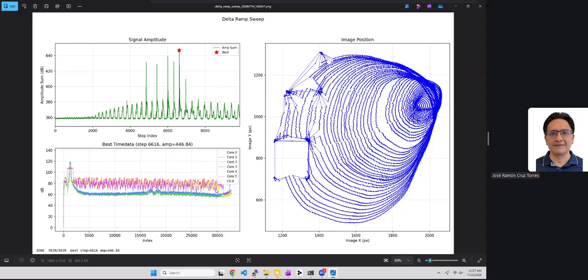It starts running immediately on the equipment. It starts from where it currently is and just starts spiraling out. You can bias it. If you want to scan over here, you can move your end face such that it starts here and the scan will start from here. Although, make sure it's still within the actuator's range of motion or you'll start getting really weird stuff.